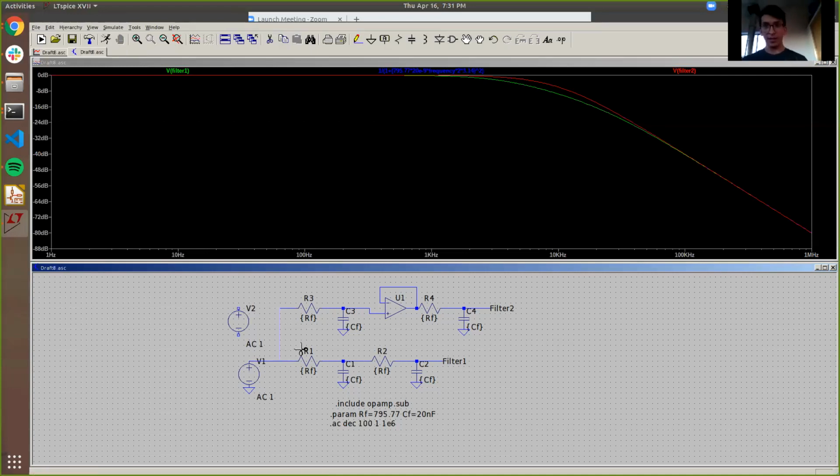You could set as many voltage sources as you want down, and you could type in commands for them to run differently if you'd like. I have had circuits where I've had like 4 voltage sources. One is like a 5-volt rail, one is like a reference rail, another one doing the thing that I wanted to change over time. So you can have as many as you want, but if you wanted to simulate 2 distinctly different circuits, you probably just want to use 2 different schematics in that case.